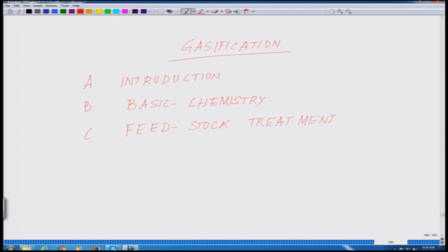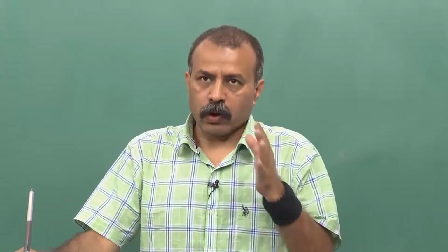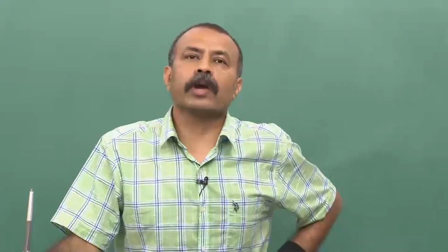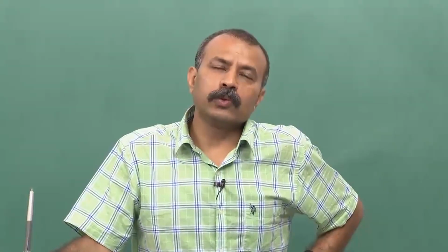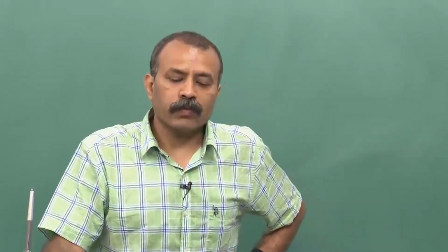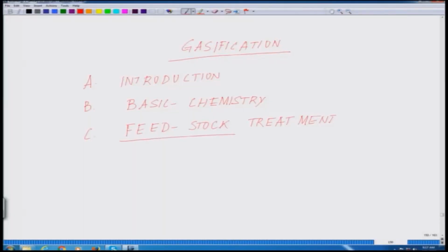In terms of the feedstock treatment, we will be talking about what you need to do before you put something in a gasifier, or the whole assembly in which you are converting the biomass to gas. You need to do some form of pre-processing of that biomass or the feedstock. Here what we mean is basically the biomass. So, it is biomass pre-treatment or biomass treatment, whichever we call it.